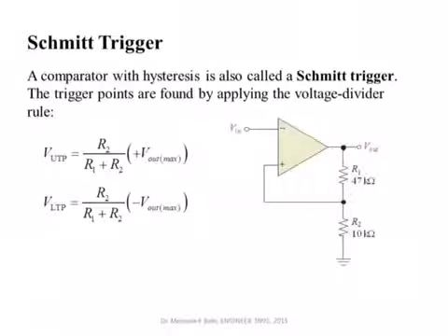One of the interesting circuits we used for hysteresis is called the Schmitt trigger, and the theory of this circuit is achieved by using positive feedback. We have here a positive feedback. Look what's happening. Assume that V out is positive. Then the voltage here at the positive terminal is simply a voltage divider. So it's equal to V out multiplied by 10K over 10K plus 47K. So I'm comparing Vn to this voltage here, V plus. This is a positive number.